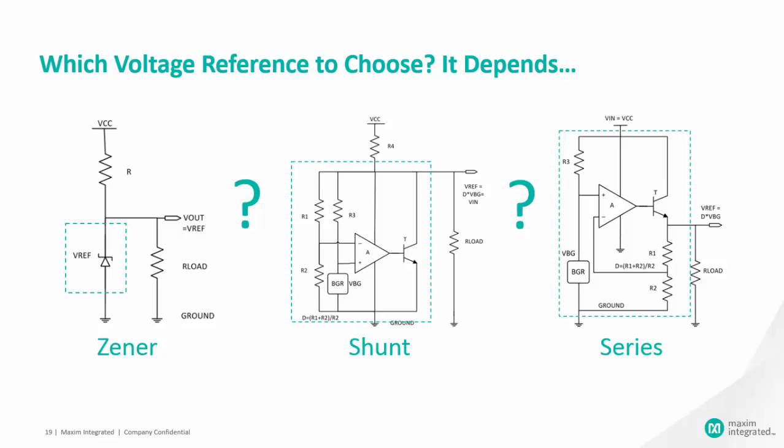However, in the presence of a load with current peaks of short duration, the shunt regulator's resistor has to be sized for peak current, forcing the excess current during normal load conditions to be taken by the IC. This results in high power dissipation inside the IC, so in this case, a series regulator is preferable.